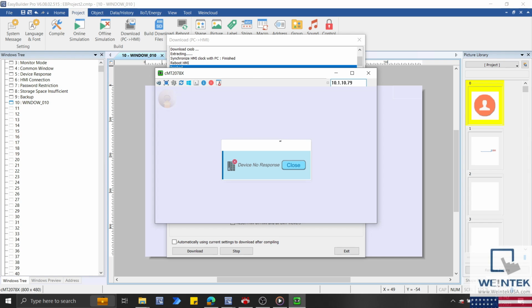To create our Codesys project, I'll begin by connecting my PC to the HMI's LAN 1 port. This port is assigned to Codesys after Codesys activation, and the IP address of Codesys can be configured within the Codesys tab of the HMI settings menu.